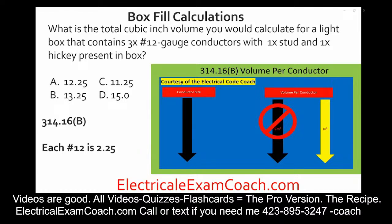Now let's count our conductors. We know that we have the 3 number 12s originally, but now we have to deal with the studs and the hickeys. Our code states that for each stud and each hickey, they count as 1 each based off the largest conductor that's in the box. In this case, we only have number 12s, so they're going to be grouped with the 12s. So that lets us know that we have a total of 5 number 12s. That's what I meant by we're converting everything back to conductors, and then we can do our multiplication. We take those 5 number 12s, multiply it by the cubic inch volume for 12, and we end up with 11.25 cubic inches, and we would select C.